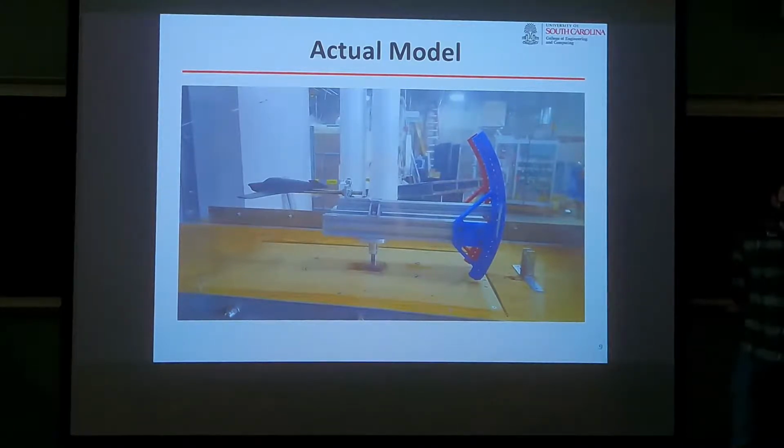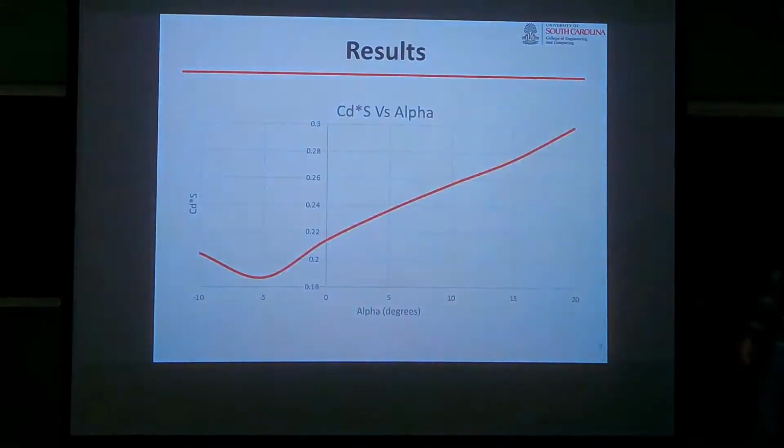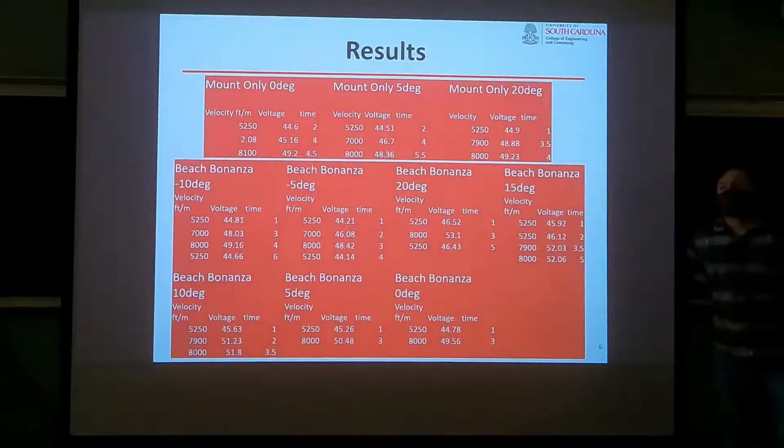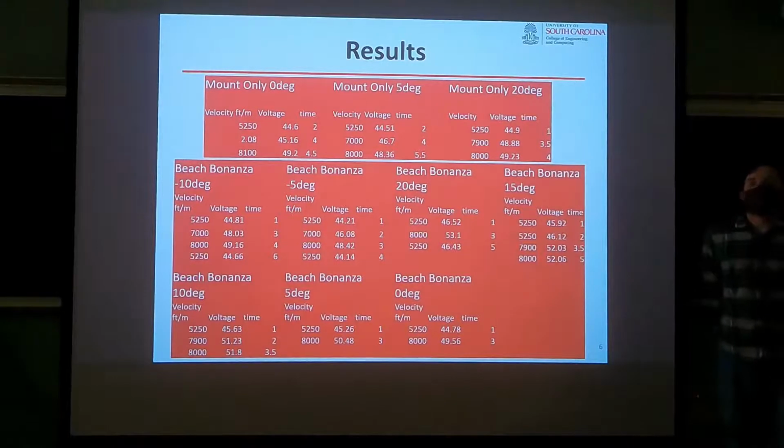So on your results page, you set a voltage value. I'm confused about what the voltage is and how it works into the calculation of CP. The load cell that we have is uncalibrated, so it doesn't come with any data of what force is my readout.